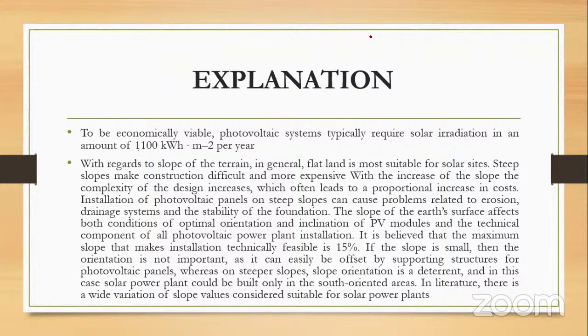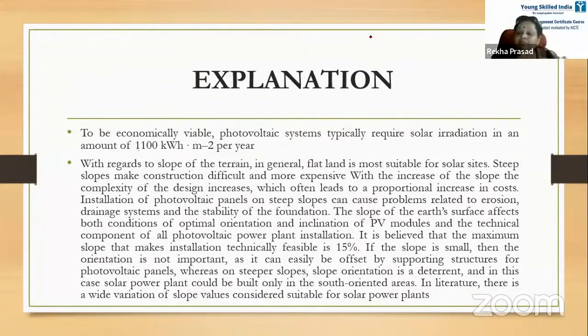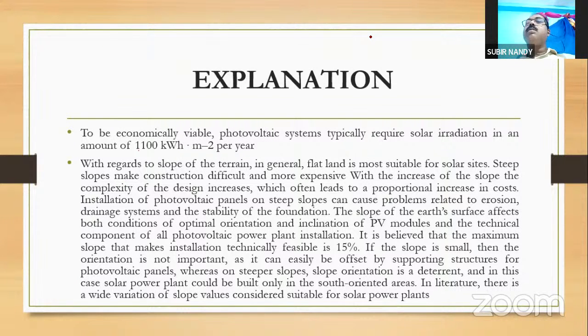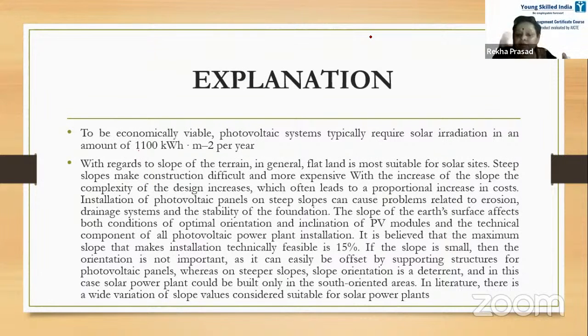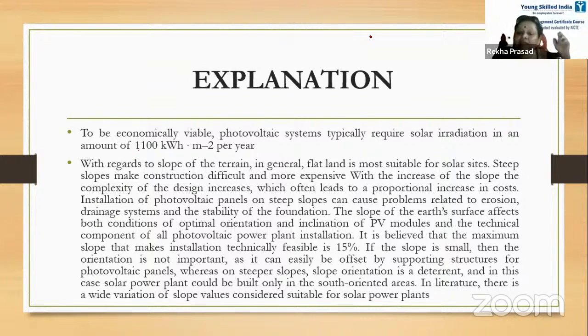Up to 15% slope, technically you will have no problems. If it is more than that, there will be technical problems. There will be environmental problems too. It will lead to erosion, drainage system, stability of the foundation. All these things will be affected. So that is why we should not go to a very hilly area or where the slope is very high.